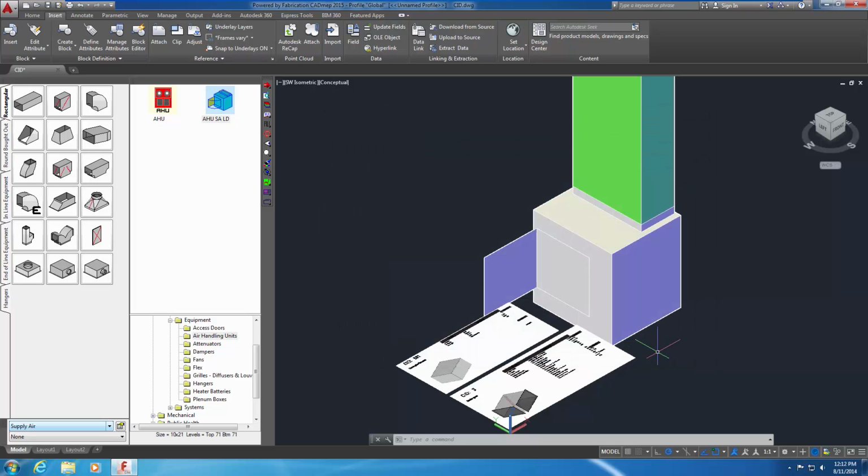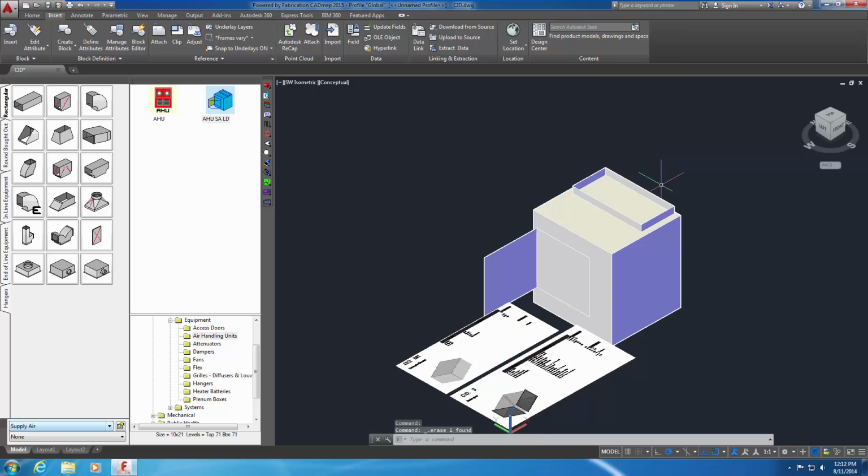Notice that the duct item has changed to meet the new specification. The connector type matches the AHU and the length adjusts to the new specifications. Typically, your CAD manager will set the connector types in the services specifications. The previous steps placed a duct onto the AHU using the attacher arrow. You now learn to connect a design line to place ductwork onto the AHU. Delete the duct item. Close the folder's interface by clicking the X at the top right of the window.